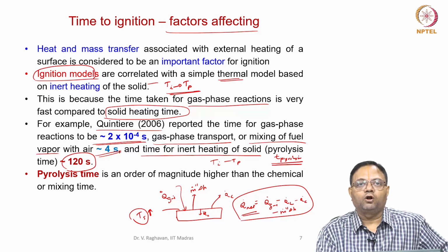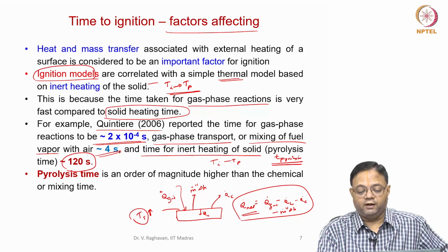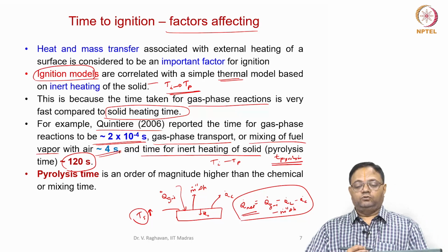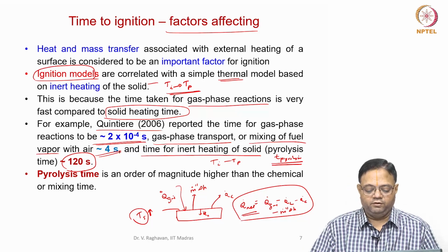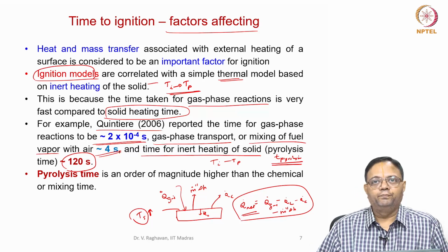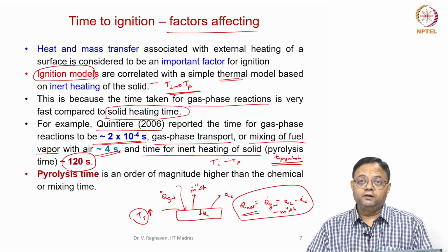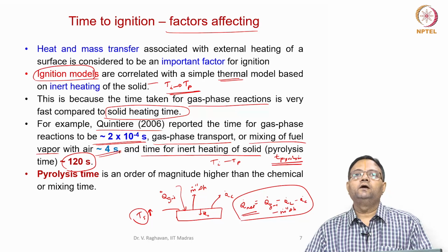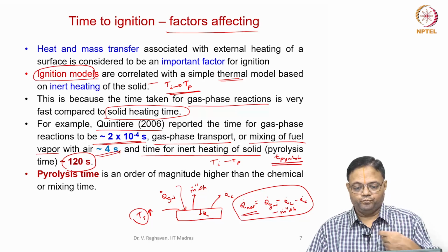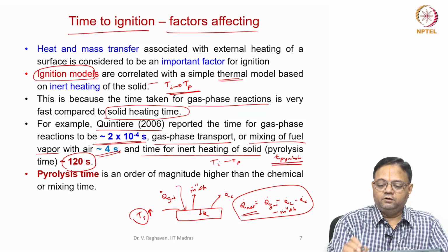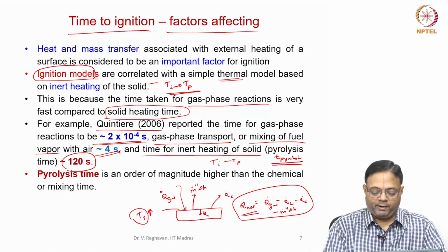Then the mixing time is order of 1 second, and the pyrolysis time is order of 100 seconds. That means the pyrolysis time will be the rate controlling. That is, the heating of the solid is the main thing here. So, time to ignition is basically controlled by the pyrolysis time.